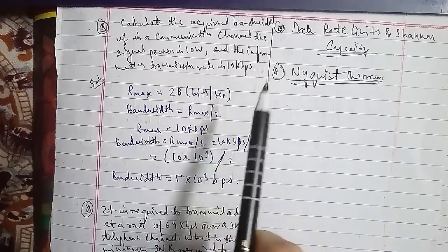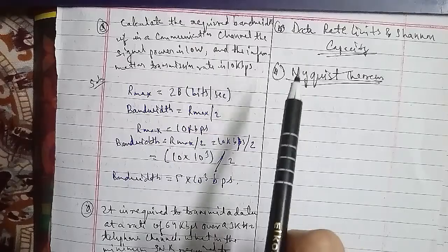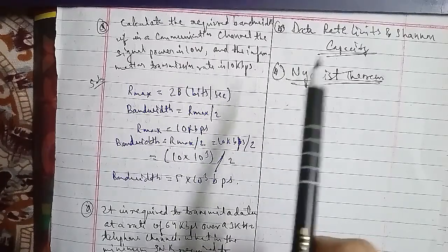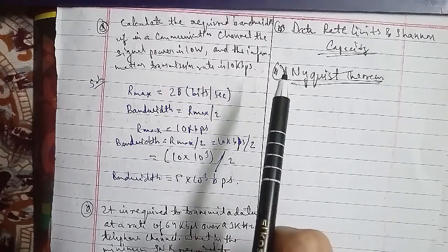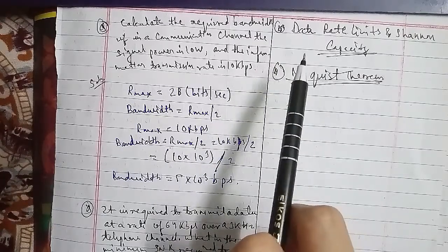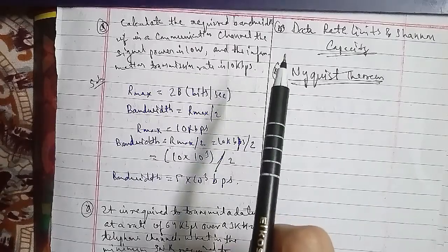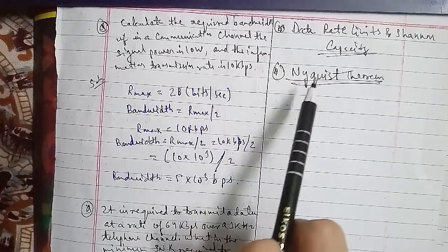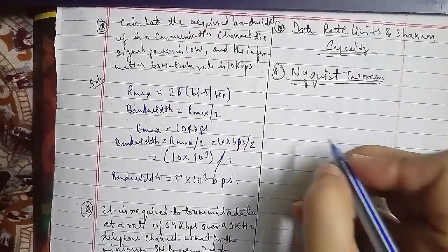So for that, first you have to know about the Manchester encoding. In the Manchester encoding, the duration of the bit is divided into two halves. The voltage remains at one level during the first half, and moves to the other level in the second half. The transition in the middle of the bit provides the synchronization, and the minimum bandwidth of Manchester is 2 times that of NRZ.